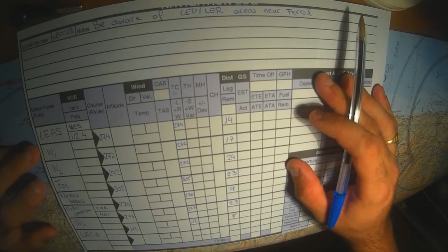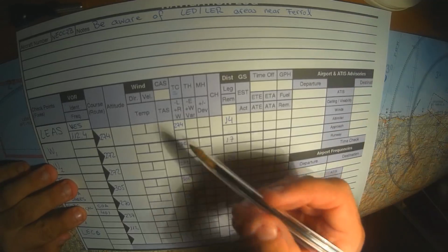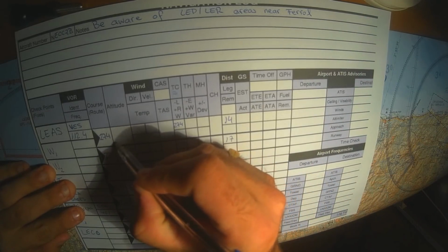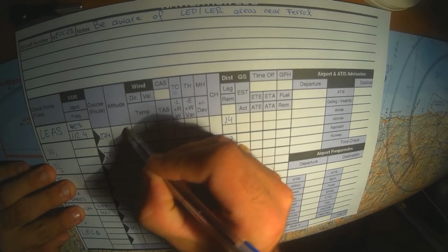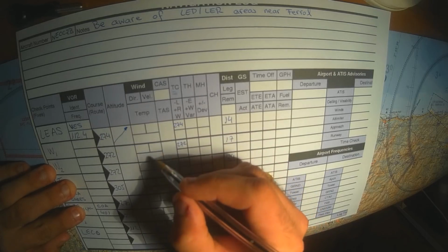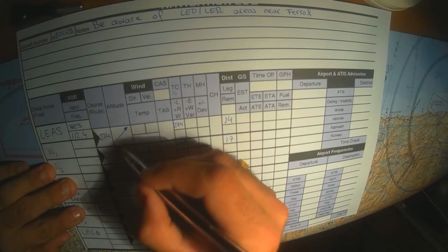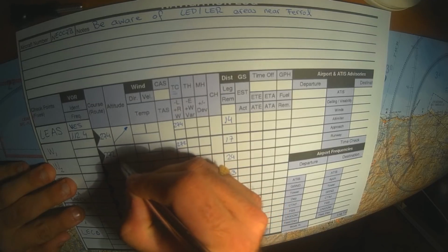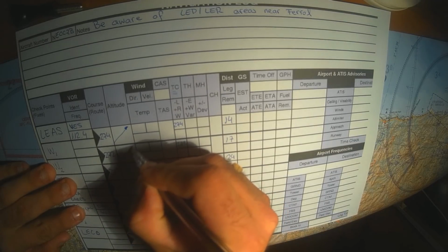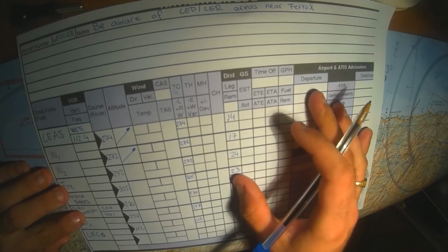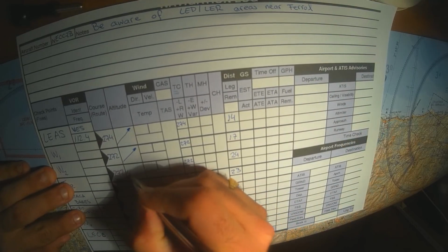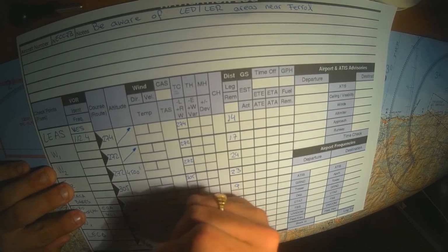The next column is about the altitude. We could be very precise with the crossing altitudes at every single checkpoint, but that wouldn't make much of a difference. I personally like to point the climbs and descents just with arrows to know what the aircraft altitude is. Following the famous semicircular rule, we should be using even altitudes, so we decide to cruise at 4,500 feet.